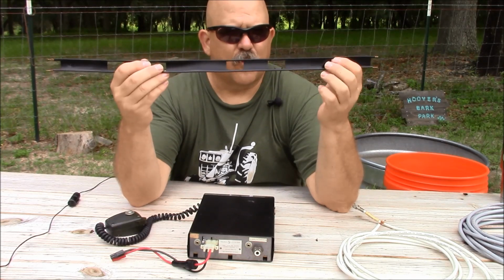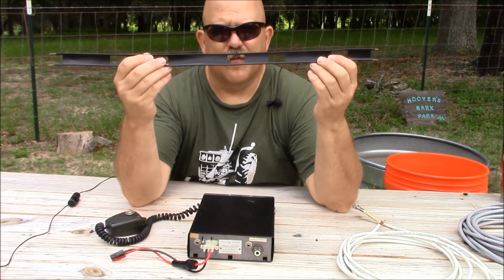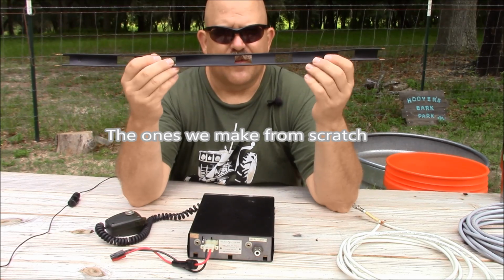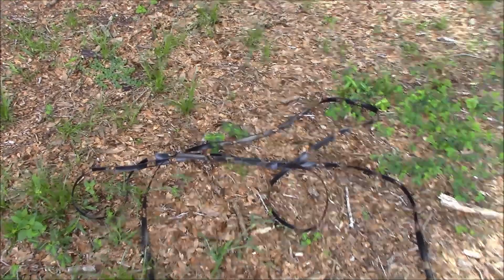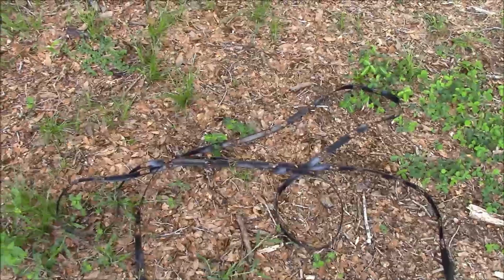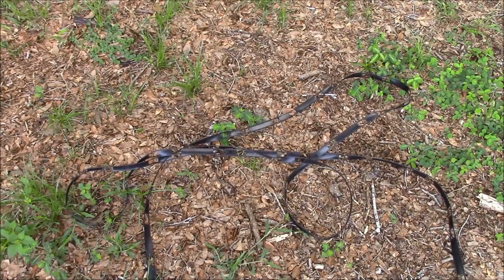And some of the examples we're going to work with are between 100 and 150 ohms of impedance when we're making our own feed lines. Now, utilizing balanced feed line requires some attention to detail on routing the cable. Balanced feeder should not be coiled up on itself like this. This should be laid out straight.